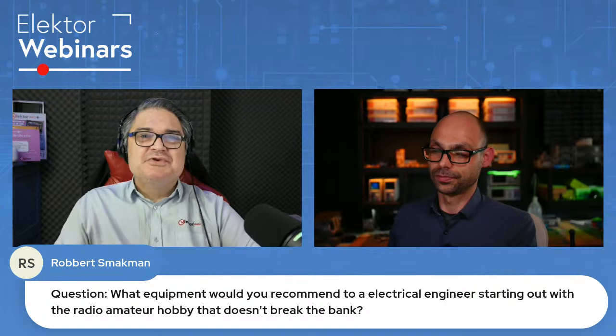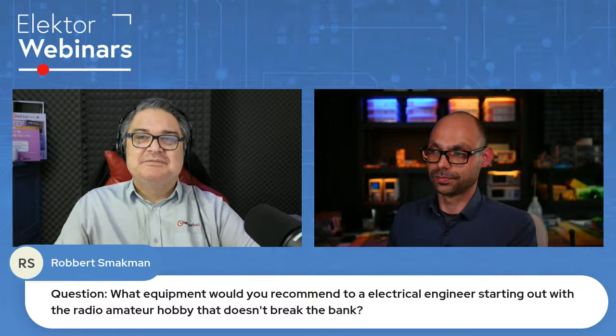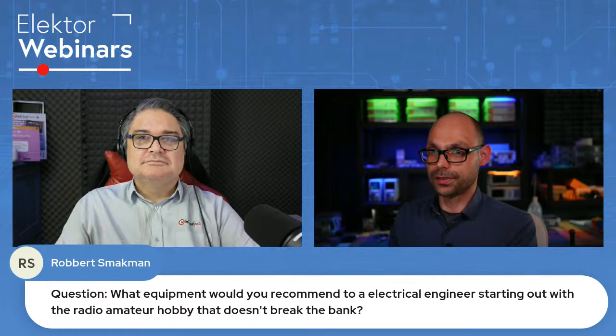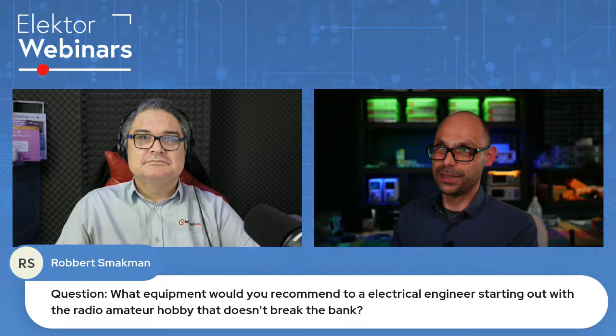Robert wants to know, what equipment would you recommend to an electrical engineer starting out with the radio amateur hobby that doesn't break the bank? Well, besides the obvious, which I think Robert is not asking, which would be the radio and a good antenna, it would really be a spectrum analyzer. And if you can't afford that, a tunable power meter, or at least some sort of detector and very sharply tunable filters. But a spectrum analyzer, especially if it has a tracking generator, is good for everything. If you don't have an SWR meter, you can even get impedance, at least in a scalar way, get one. They are really not that expensive, as the Tiny SA Ultra shows. That's the one thing I would say, get it.